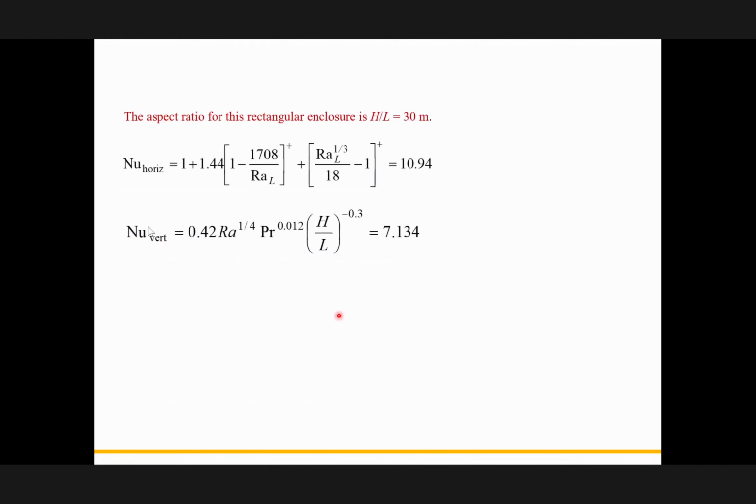Therefore, yes, we use this correlation here, but one assumption that we make is that it can be applied for air also. But in reality, the Prandtl number has to be more than 1. In our case, the Prandtl number is 0.73, which is less, but we assume that it can still be applied. In all the equations there is some error; by using this one, we make more error.